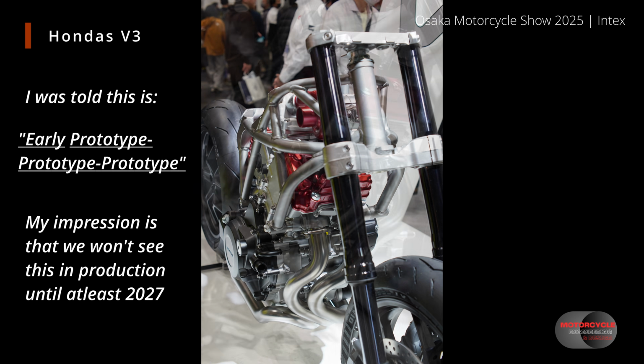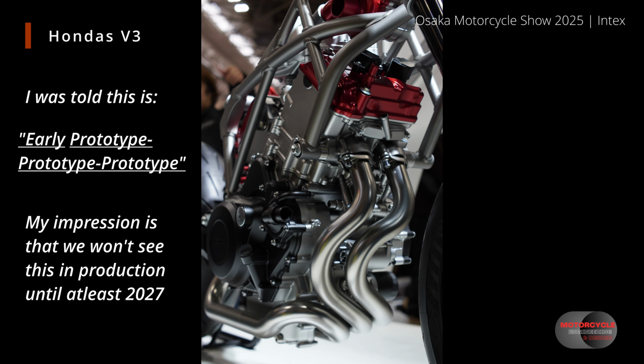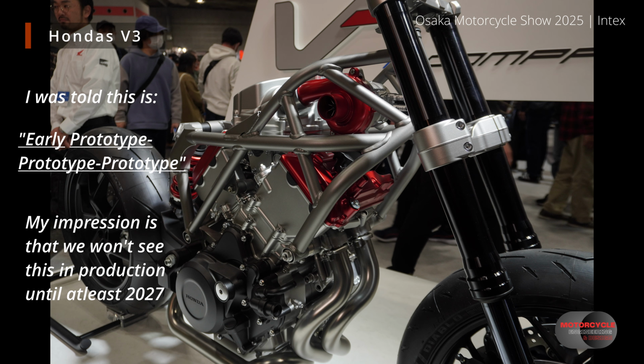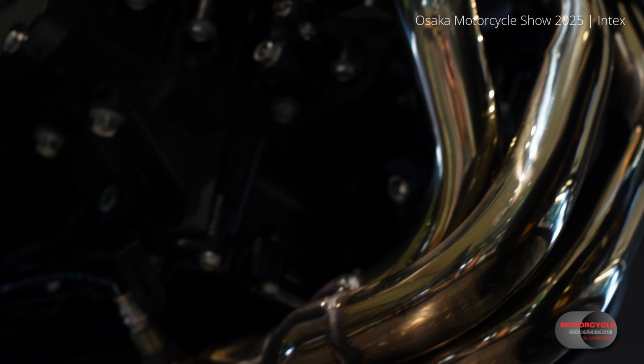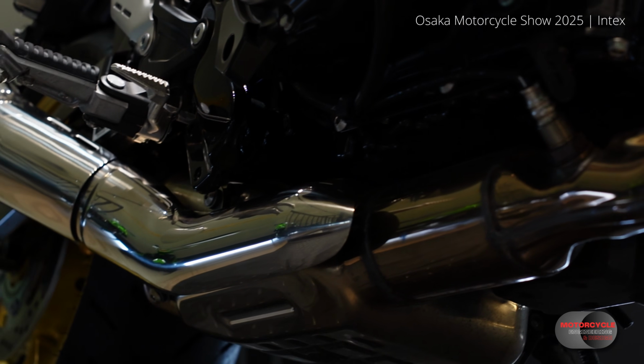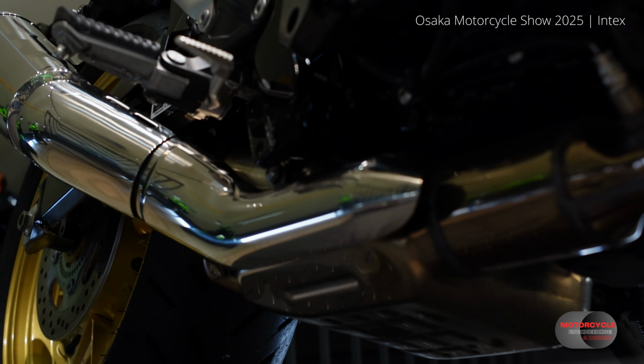So pulse tuning is all about sizing the diameter and the length of the primary pipe, or depending on the engine, the secondary pipe as well, in order for the pulses to arrive back at the exhaust valve at the ideal time. This is not going to be the same throughout the whole RPM range, hence why we have to select where we want it to be tuned for. Okay, so we'll revisit this again at the end, but let's for now get onto some 3D modeling.